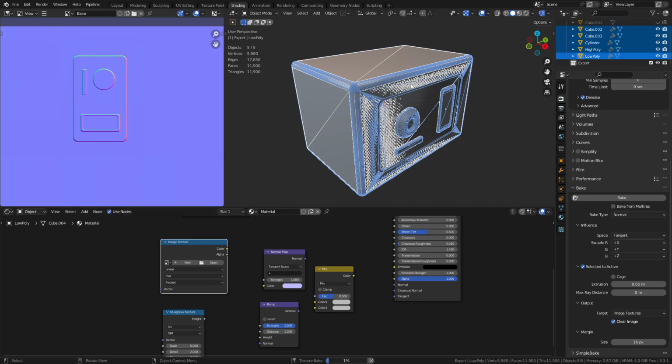We can, of course, detail this thing a lot more than this and have a lot of fun with it. But for this demo, I think we get the idea. You could pretty much click out at this point. That's how you bake your objects to a selected object, or active object. The selected to the active object, should I say? Technically, what it is.